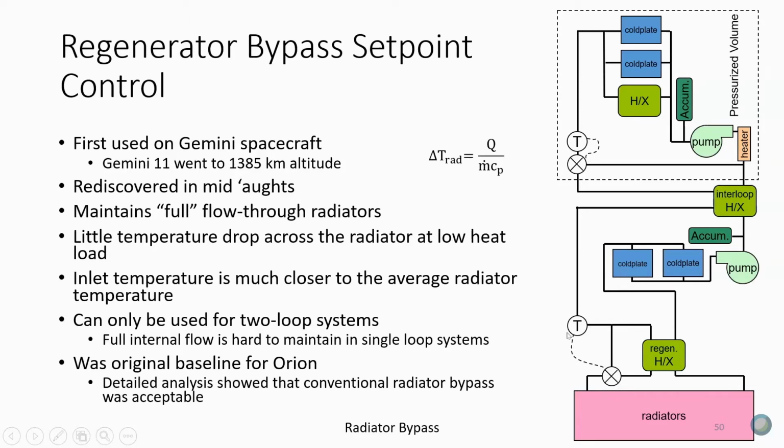Okay, so I just pulled the slide back. The radiator inlet flow goes through the regen, goes through the radiator and comes out here. So you have a choice of either flowing through the regen or bypassing the regen to maintain this temperature where you want to be. Today we would probably put the flow control assembly over on the right side, on the warm side, just so you're not controlling this crazy cold fluid, just for materials compatibility and your control valve and such like that. But it's transferring heat between the radiator inlet and the radiator outlet.